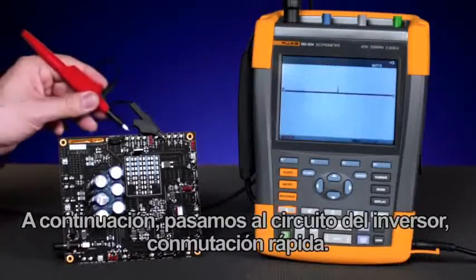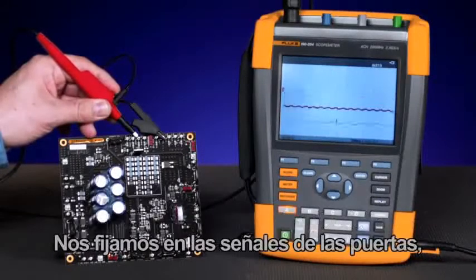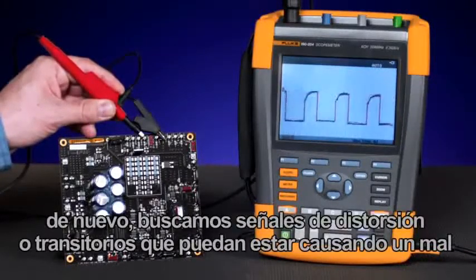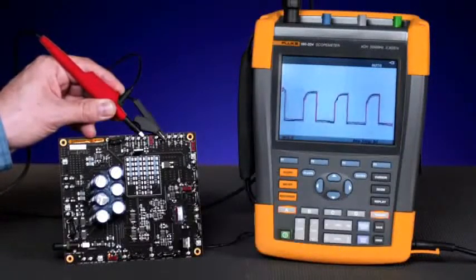Next, we'll move over to the inverter circuit, looking at the fast-switching electronic gate. Looking at the gate signals, the output pulses, and the high-frequency pulses, again, we're looking for any signs of distortion or transients that may be causing a malfunction on the output of the switch.